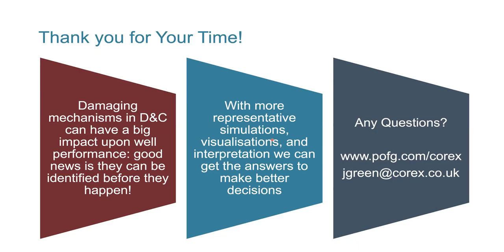So yes, formation damage is extremely relevant, but the point I made at the midpoint was you want to make sure your scope is reflecting your reservoir. The way you design the test should really reflect the reservoir type, and you might do a slightly different test for fractured chalk versus a matrix chalk, for example. So there are things to think about.